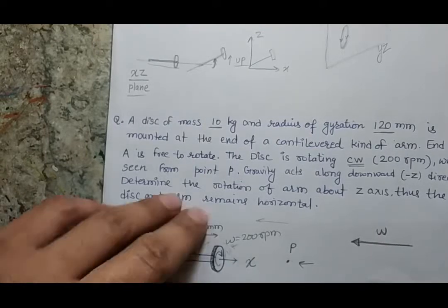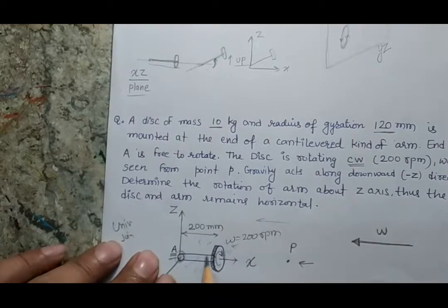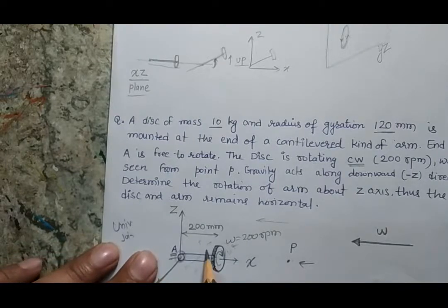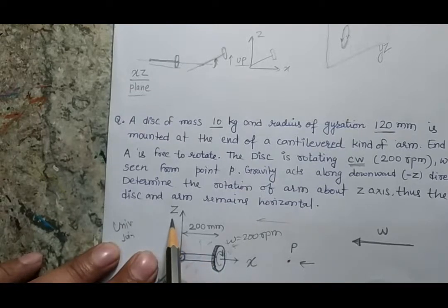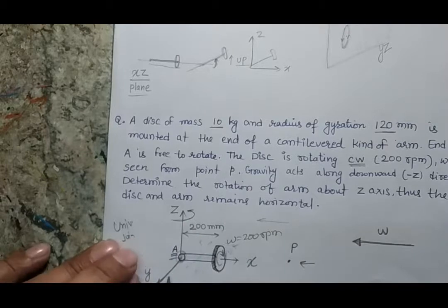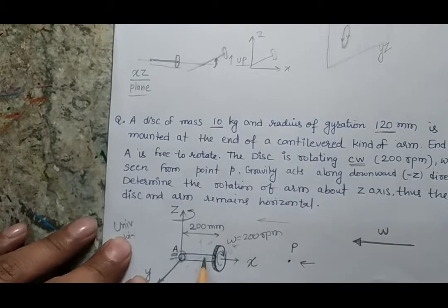Now it is saying that this complete body is just free to fall down, and if I give a precession about this axis, because of my precession there will be a net gyroscopic torque about the y axis, which will lift the rotor.